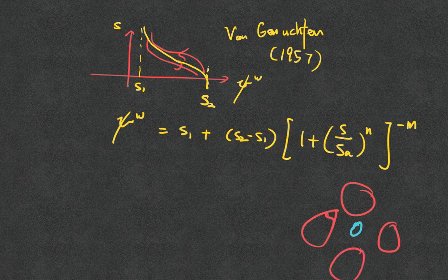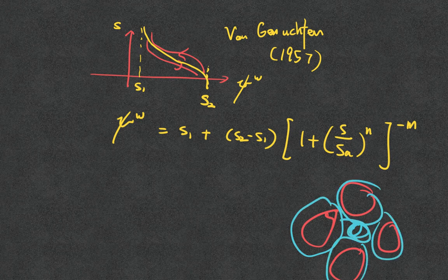Okay, what happens to the ice crystal is that it is not directly touching the solid phase. This is called the pre-melting theory. The reason is that the surface energy difference allows a thin water film to form between the ice crystal and the solid. So the ice crystal is not touching any solid, and hence it can transport in the void space. And this is actually the assumption of the water retention curve.